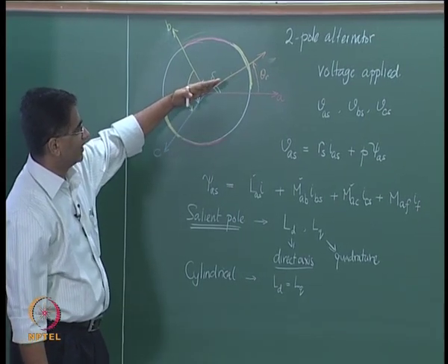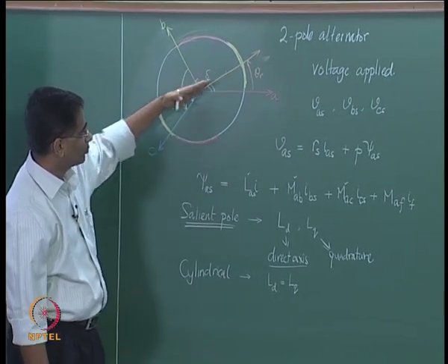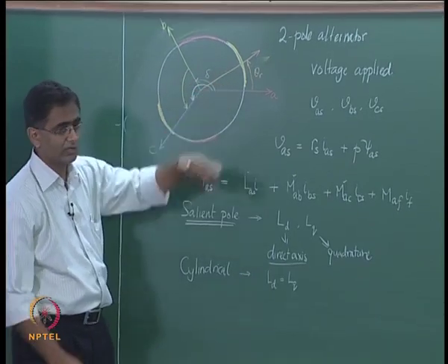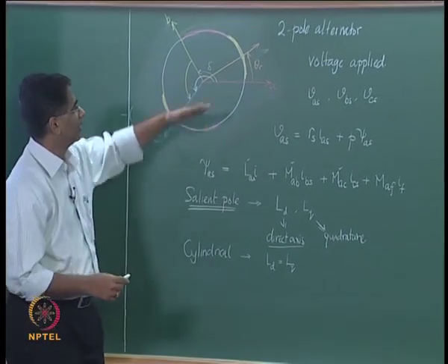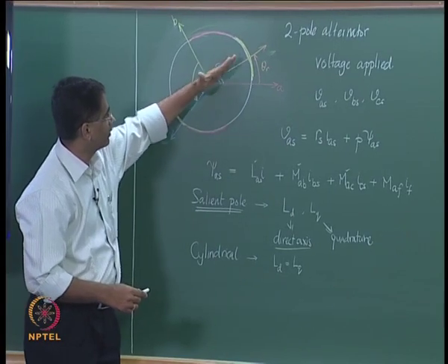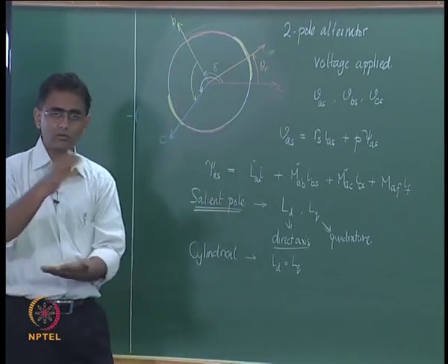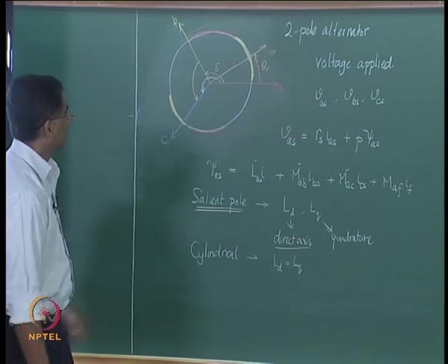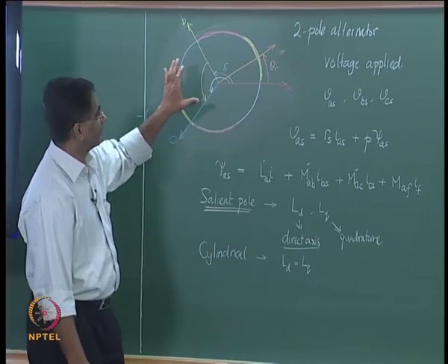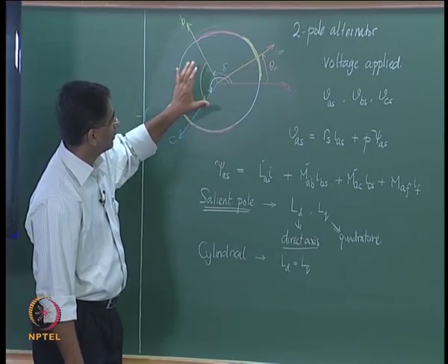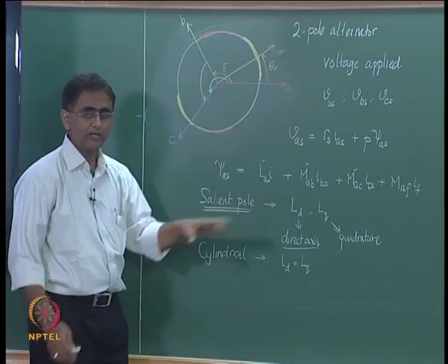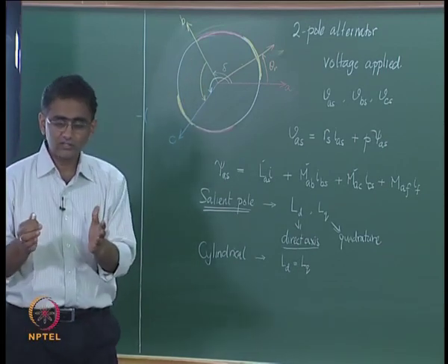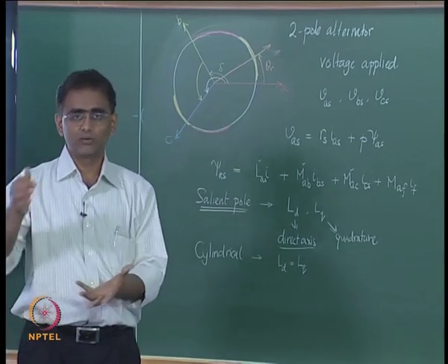and we have said that the field produced by the salient pole rotor is primarily a DC field, and the field bodily rotates with the rotor as the rotor moves. If that is the case, then the field generated by the field structure is not going to change with respect to time.